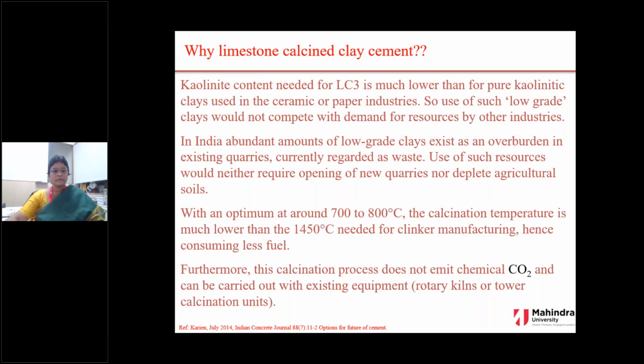And the other thing is, the kaolinite content needed for LC3 is much lower than pure kaolinite, which is used for the ceramic or paper industries. The clays used in LC3 do not need to contain pure kaolinite.